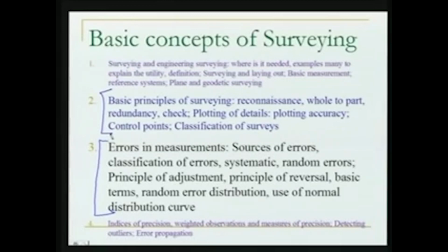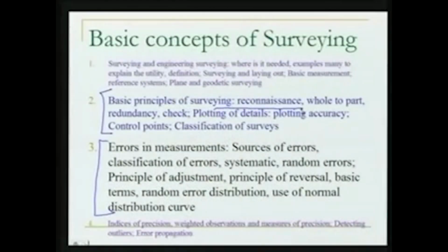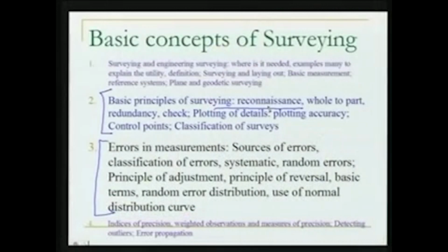These are the principles which we should always keep in our mind whenever we are going for surveying, because these are very important points, and they control the kind of work which you ultimately produce at the end of your job. Well, number 1 is the reconnaissance. In our last video lecture, we started with an exercise in which there is a little ground and we want to make a map of that ground. So what all steps are involved? The very first one was recce survey or reconnaissance.